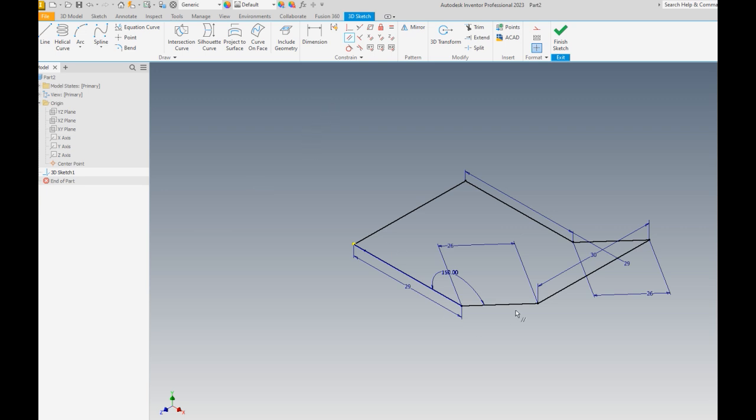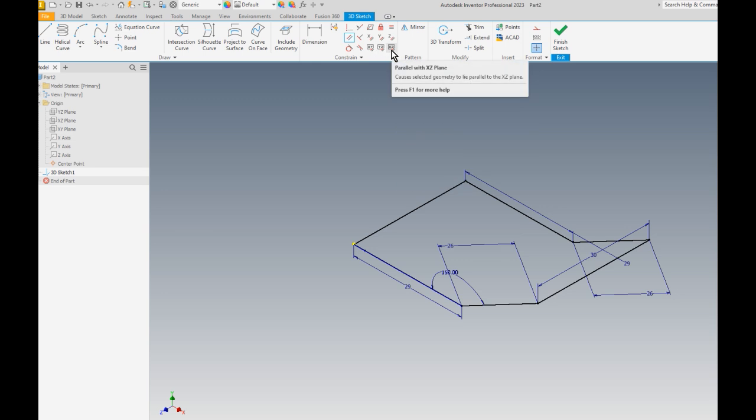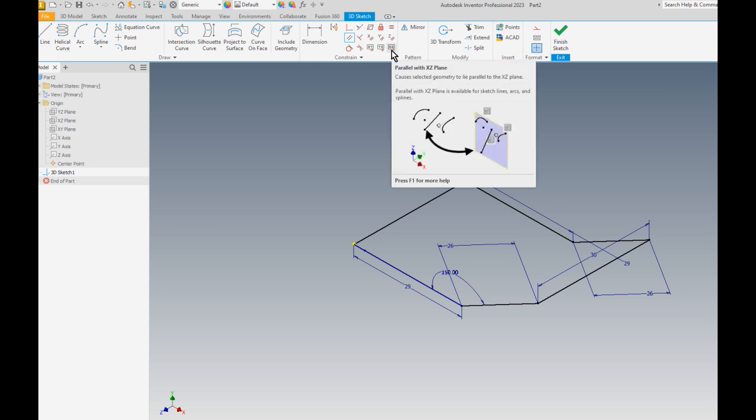How do we eliminate those degrees of freedom? We have this line actually follow, or be parallel to, the surface or the actual plane that is incorporated with this. Now we can use perpendicular, there's a lot of ways, but if you take a look up here, there's a really nice set of tools. So parallel to XY, parallel to the YZ, and parallel to the XZ.